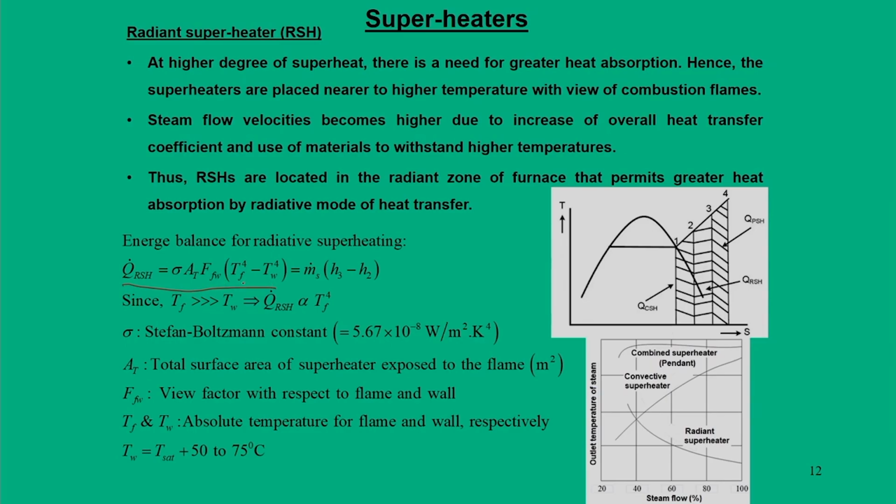So, this is the radiation heating, and using these equations it can be correlated with the rise from point 2 to 3, because from 2 to 3 we normally use a radiant superheater. And the radiant superheater means that the steam is allowed to see the surface of the wall, that means at the wall the radiation is most predominant.